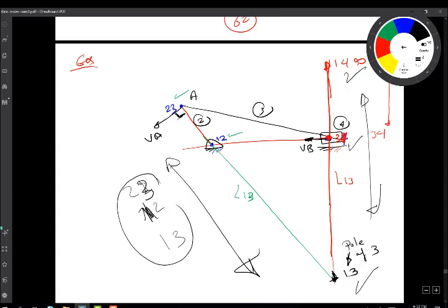Okay. How about 2 and 4? Do they share a point of common velocity, 2 and 4? This is link number 2, which is a crank, and this is link number 4, which is the slider. How to get point 2, 4? I want you to think about this for a second. Point 2, 4. Okay. Now, which direction will it be on? Well, let's find a locus, right? So, if I look at this side here, I have this here is 3, 4, and this here is 3, 2. So the common number is 3. So the missing point is 2, 4.